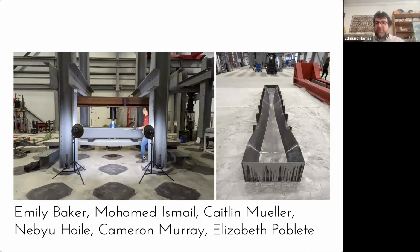And so you can model that, but then this is actually building and showing that the models are fairly conservative. So this actually was able to take 120% of the weight that the model predicted it would be able to, which is sort of what you expect. If you model something and you say it can take a certain weight and it can only take exactly that weight, your model wasn't conservative enough, because obviously, if you're building something with concrete beams, you want a nice little buffer between where you say it's going to top out and where it actually causes damage.